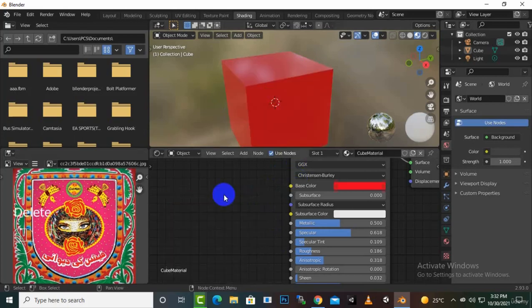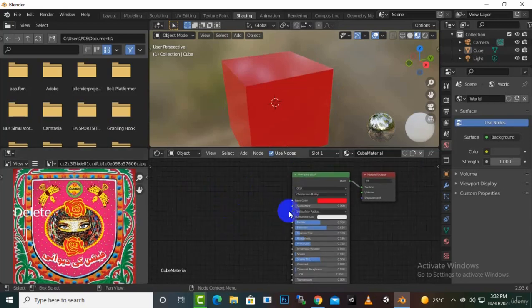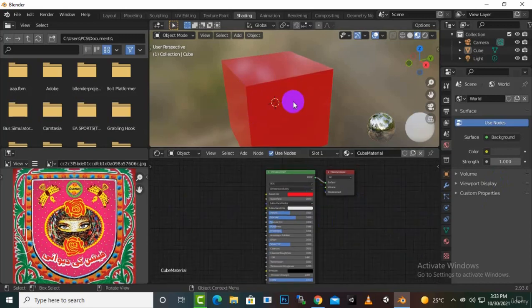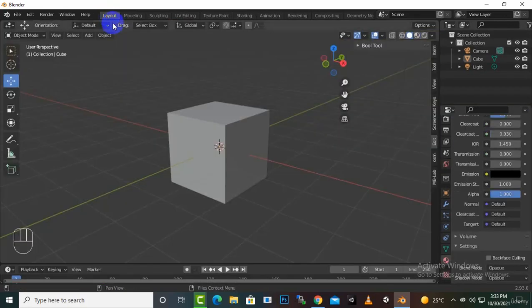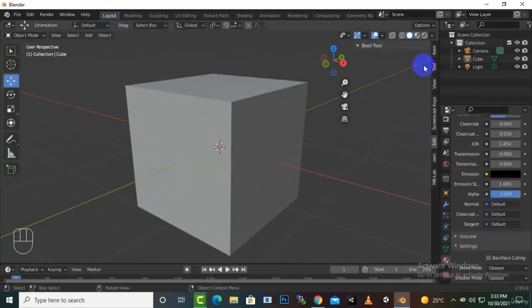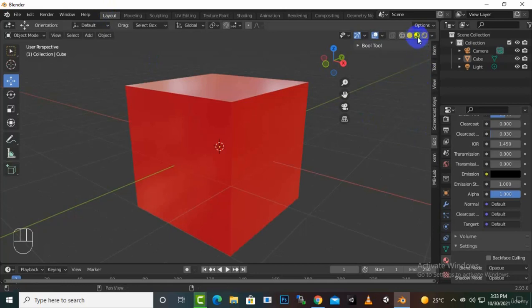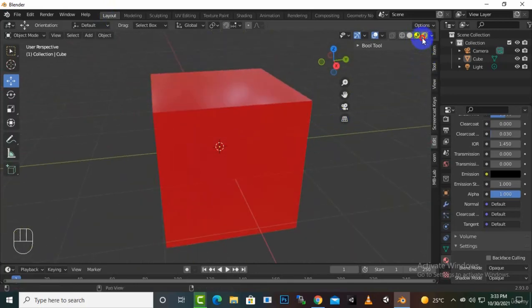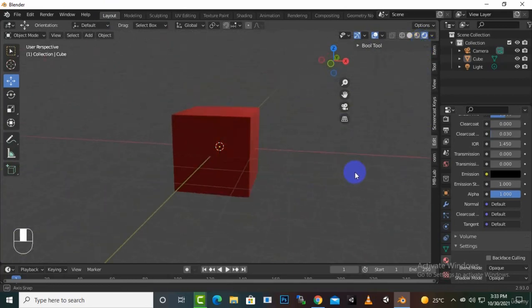So this is the benefit of this window, where we can create multiple nodes. We can even add base materials, and then normal maps, height maps, metallic maps as well, to get some better results. So if we go to layout view, and we want to see our material here, we can click here, and now this is the material window. We can press Z and go to material preview as well, so this is our material view. If we click here, this is the render view.